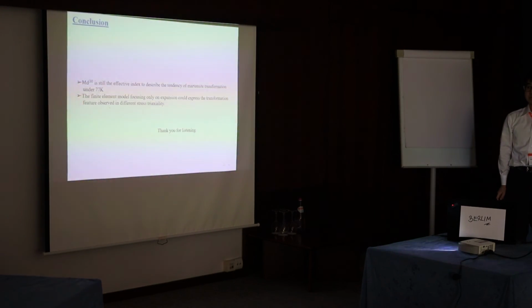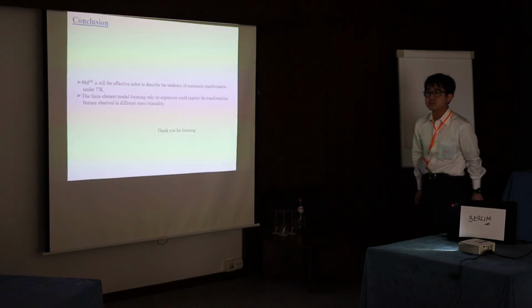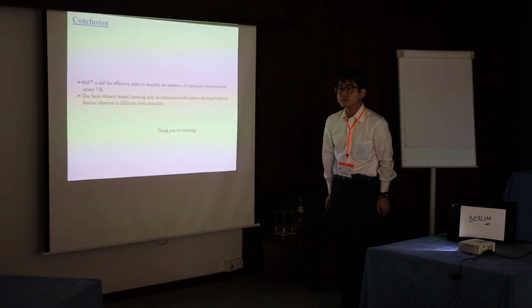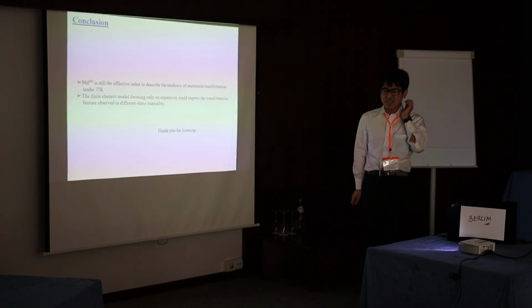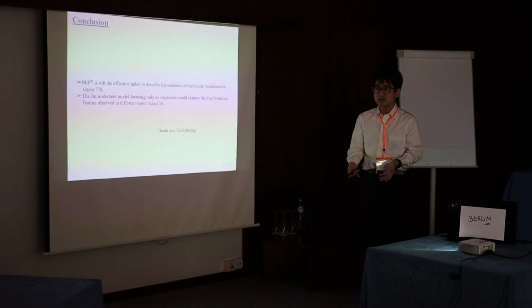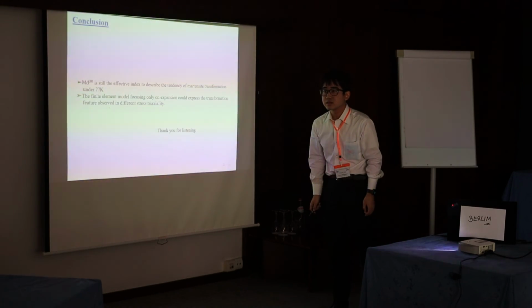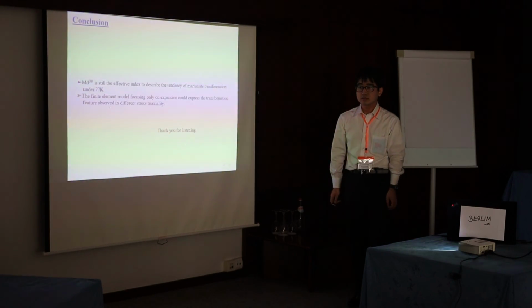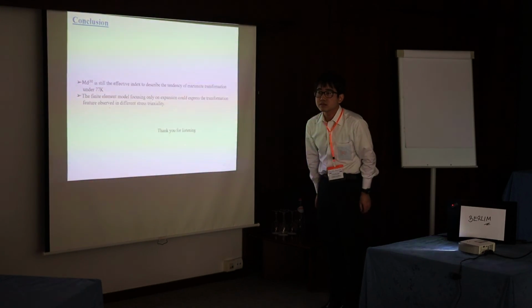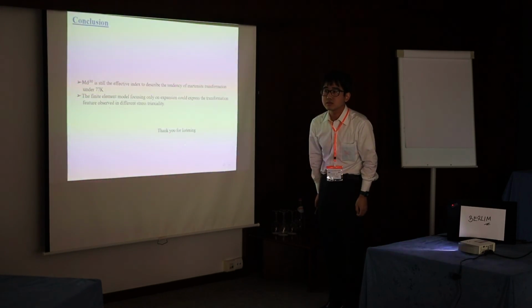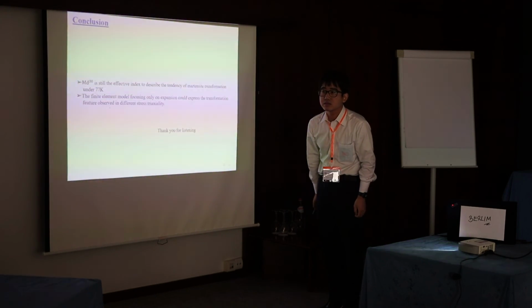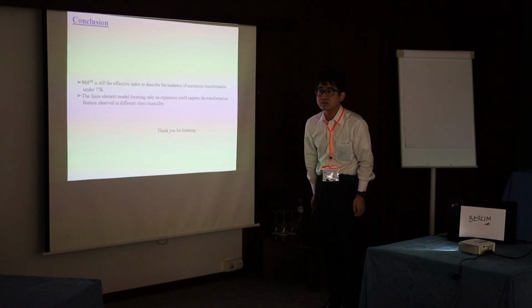Any more questions or comments? Is the toughness also important for your research? Yes, because martensite has more hardening. And you are dealing with cryogenic temperatures also, yes? Yes. And the induced martensite, we know that if we bend, if we roll, we transform austenite because you are using austenitic stainless steel. You will transform some into martensite.